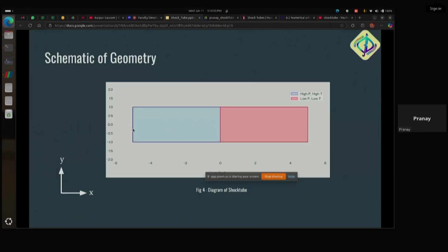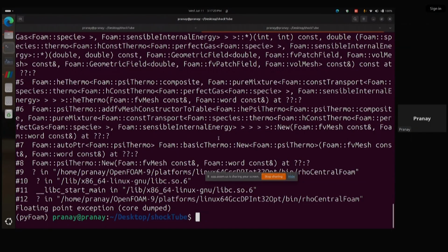Usually, the starting blue line becomes the inlet, these are no-slip adiabatic walls, and this becomes the outlet. But in our case, this is not the case. That's why we are using setFields to assign a value to the entire region, unlike assigning a value to a single edge or a single location. So we'll enter the setFields command.